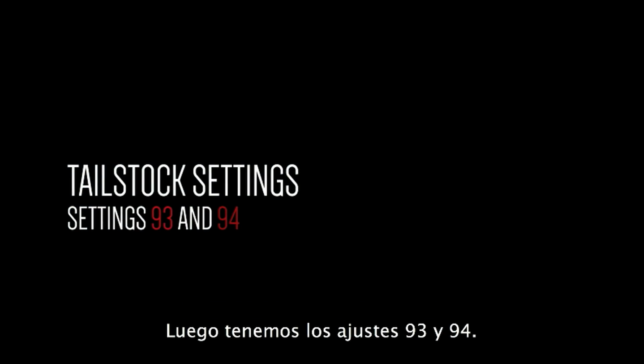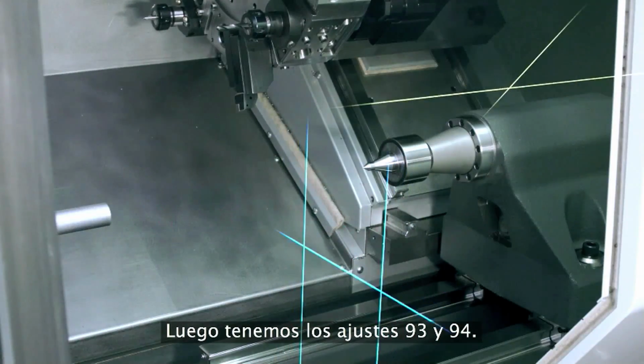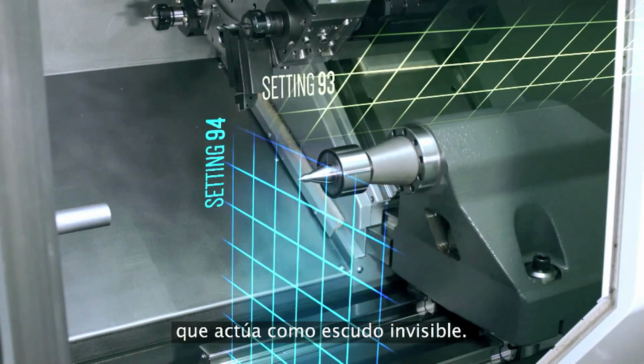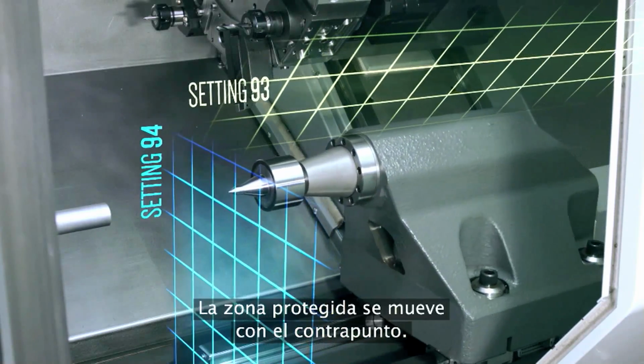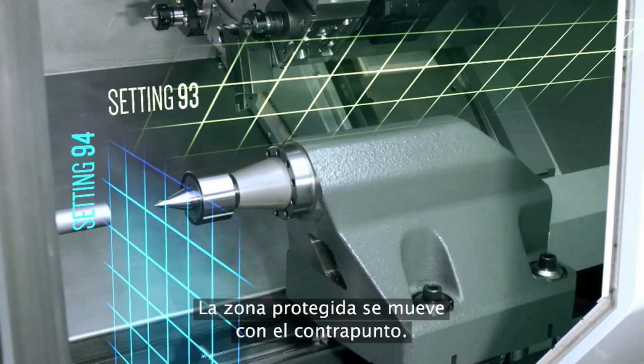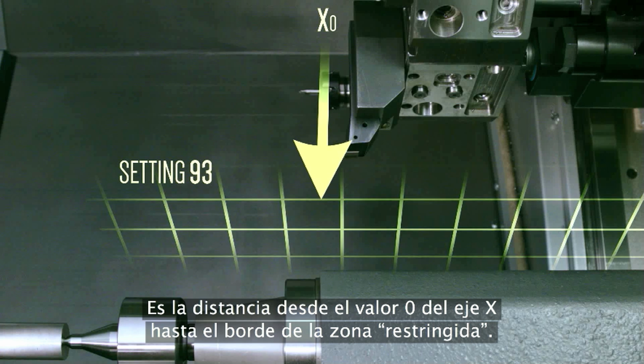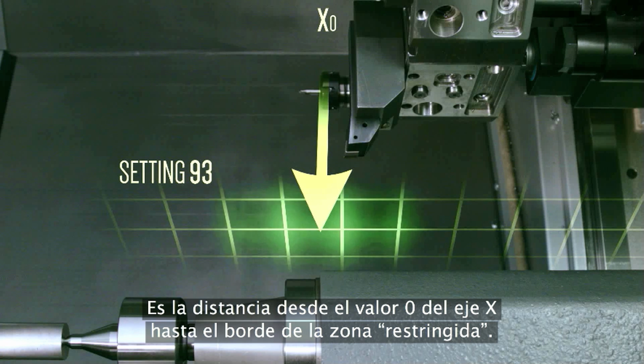Next, we've got settings 93 and 94. These define a region around the tailstock, which acts like an invisible shield. This shielded zone moves with the tailstock. Setting 93 is easy to visualize. It's the distance from x0 down to the edge of the restricted zone.